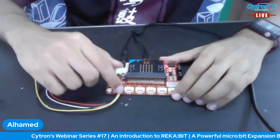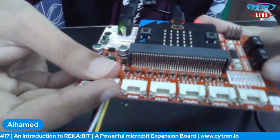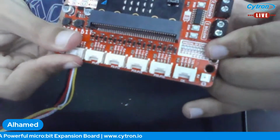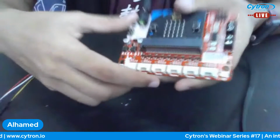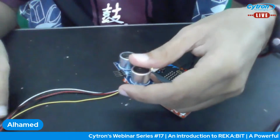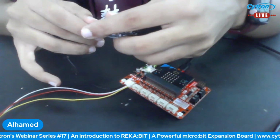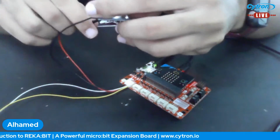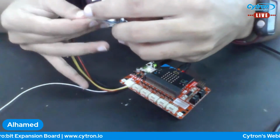And if you notice, once we connect it, we will be having this digital status. Wait, let's connect it to the ultrasonic first. So the ground pin will be connected here. Echo will be P0.